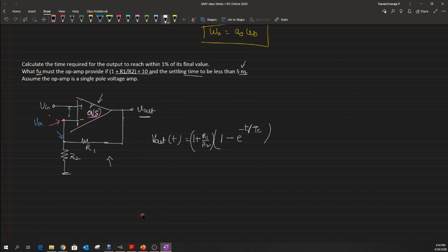Yeah. So now graphically, what has been asked and told in the first two statements here is that for a step input, let us assume the magnitude of this is equal to 1, just for ease. We know that the output will not have a similar shape or a magnified version of the same step response. Because of the limited bandwidth of this open loop configuration, there will be a kind of exponential growth in our output response, okay.